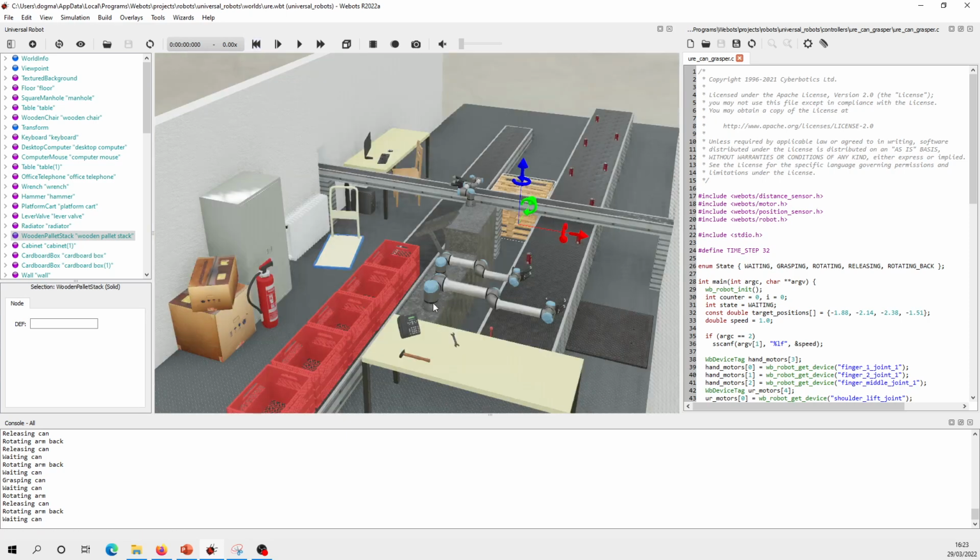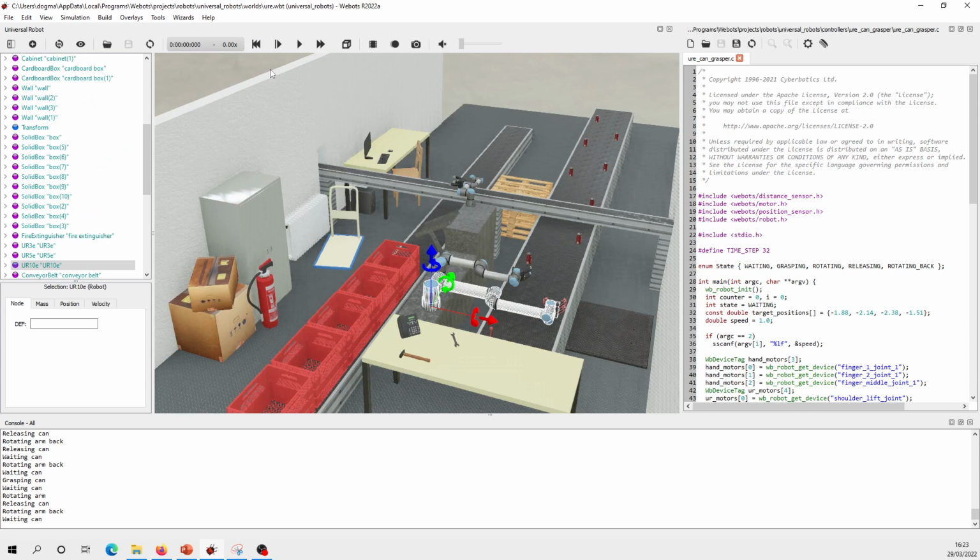If, for example, I was adding different robots and moving them around and I clicked here, it would also be saved to the origin, the start of the simulation. I will explain about this later, but you will often make a mistake that I've made many times, which is that I'm modifying the scene and I add new things and new robots, and then I press this and everything disappears and goes to the start. And this is because I forgot to save.